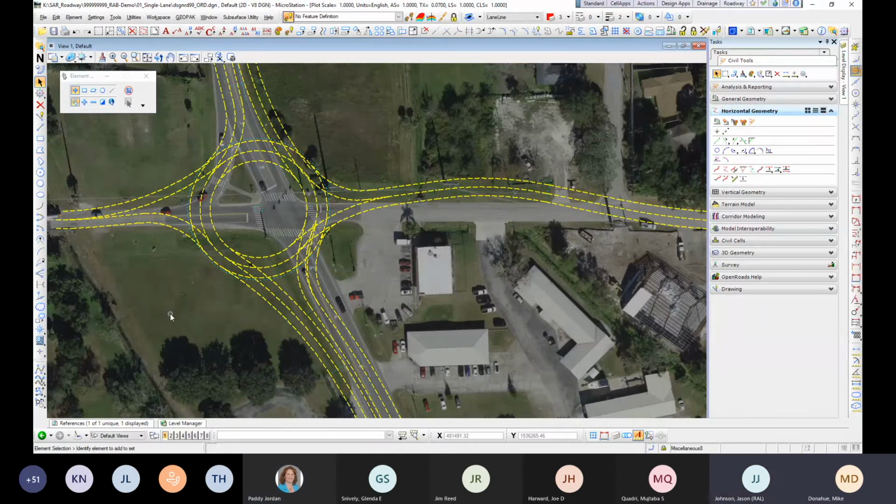And there are times where you may control the outside edge by forcing a 2% here, 2.5% here to 3% here, and then look at your profile view for that outside edge and target each one of those cross slope points and let your cross slopes dictate that outside profile. It really is very project specific. There's no blanket answer other than you've got to evaluate each line independently.